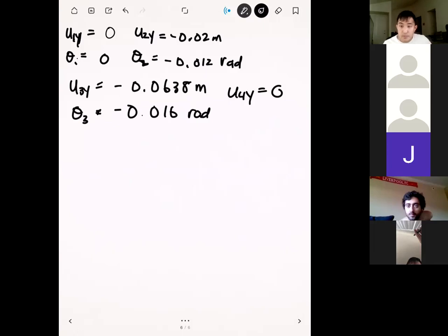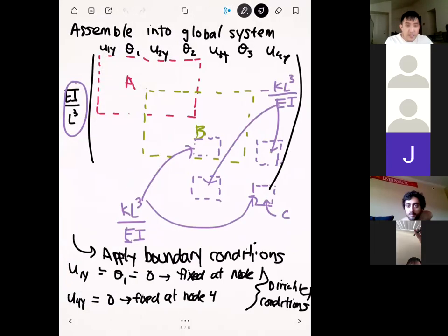Okay. All right, so the question is, is EI over L related to the moment? And so it's actually a factor that gets multiplied by the entire thing. So that comes out directly from the beam equations. And so this is just the standard form for the element stiffness matrix for a beam. And so it does partially have to do with the moments, but also the transverse displacements have a similar factor there as well. Yeah, so it comes straight out of the equations that we use to form the matrix.